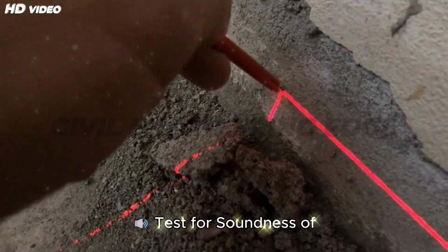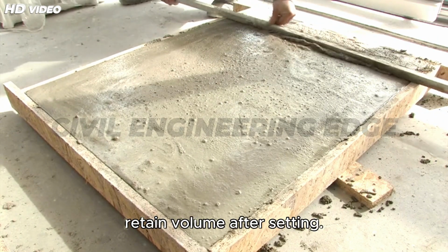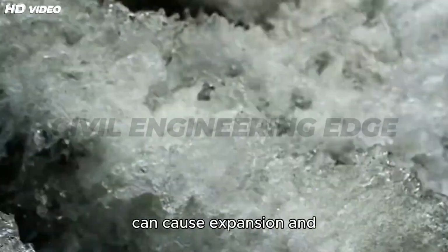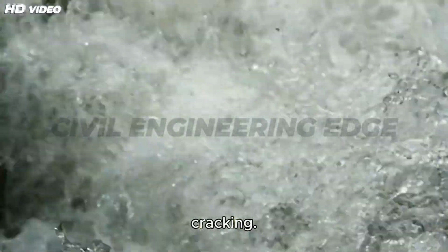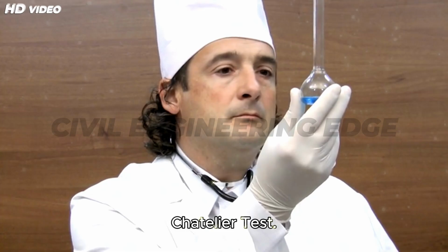Test for soundness of cement. Soundness checks the cement's ability to retain volume after setting. Unstable compounds like excess lime or magnesia can cause expansion and cracking. IS 4031 Part 3 prescribes the Le Chatelier test.